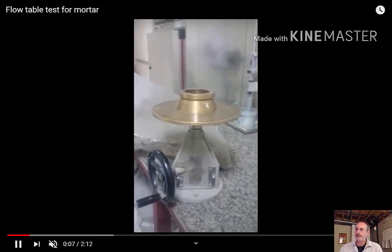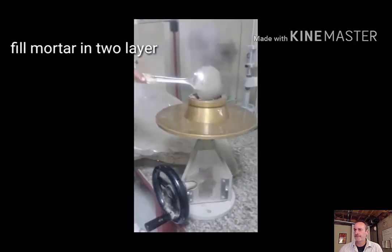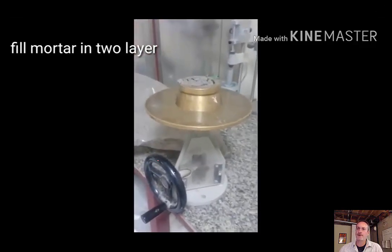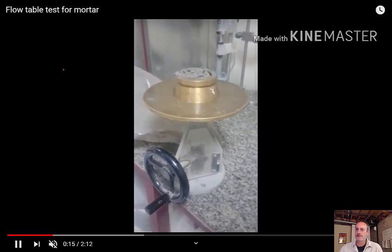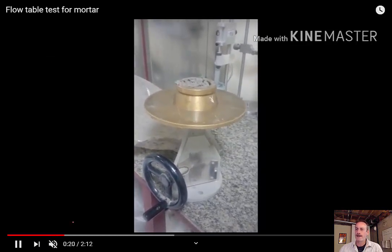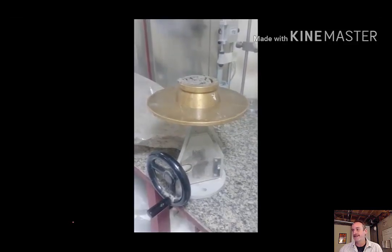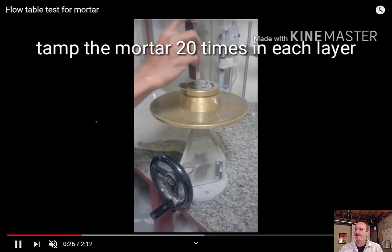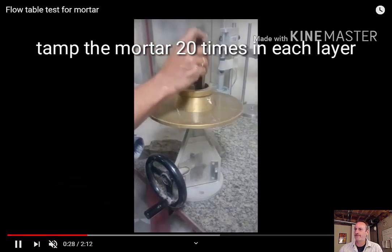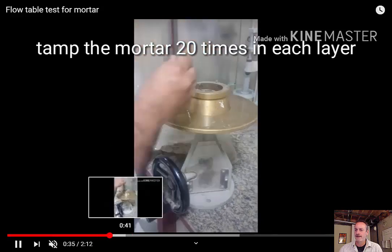And it's going to be almost similar to what we saw with the slump test, where I'm adding multiple layers. This one I'm doing 2 layers into this jar. And then just like before, where I have my rod and I would rod it 25 times, in this case what I have is another type of device, and I'm tamping it 20 times in each one of those layers.